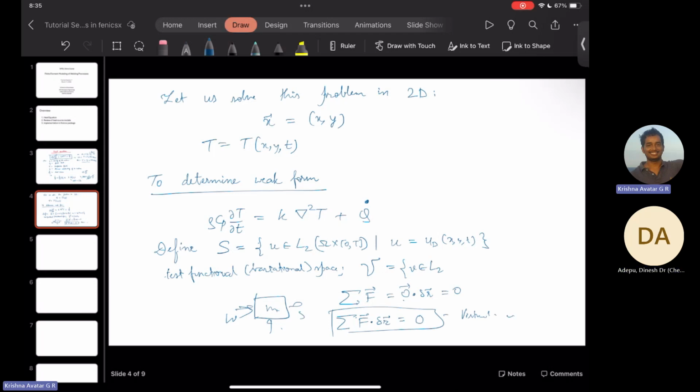If we extend it, this was a static problem. Now if it's a dynamic problem, then we also consider the dynamic forces, or the inertial forces. Inertia force is also considered some type of force, so it also goes in the summation on the left hand side here. The inertia force, mx double dot, also goes in, but it will be negative in sign. It's like we cast even the dynamic problem in a form that appears to be static in nature.